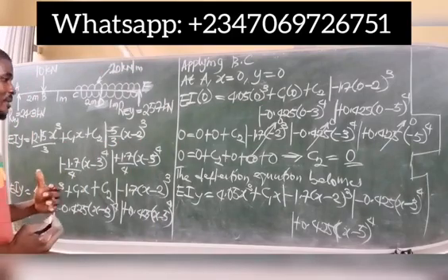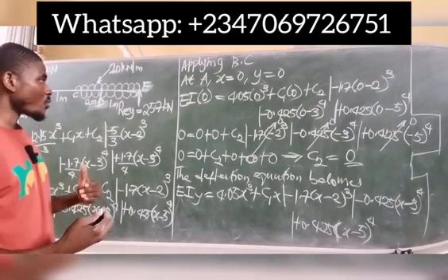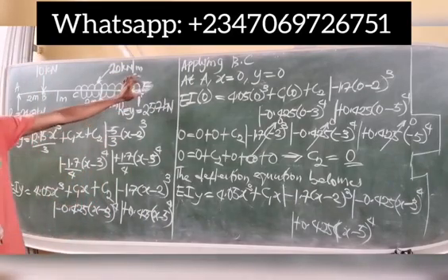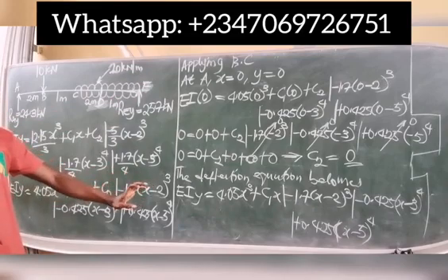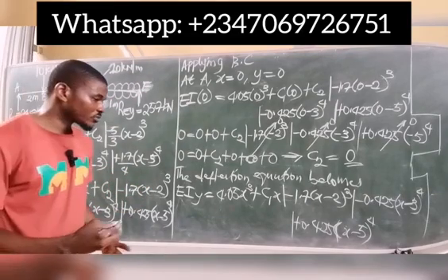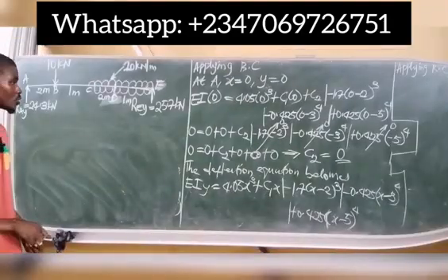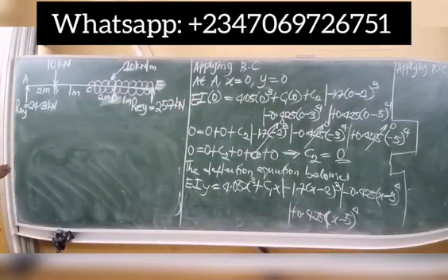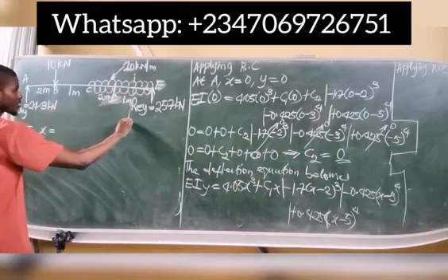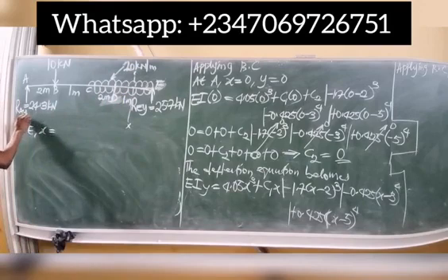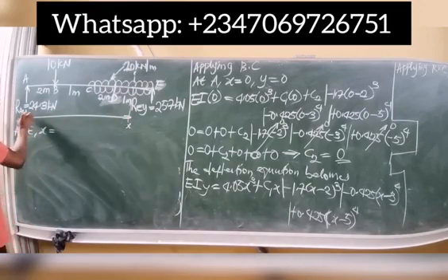So at this point now, we employ the second boundary condition. What is the second boundary condition? Simply at where? Point E. That will help us now to find the value of C1, or the first constant of integration C1. Okay, so let's do this and see. So applying the second boundary condition, which is at the end of the beam E, so simply at E, x is equal to, now remember we took a section somewhere around here, section xx, and we call the distance from point E to the point of section to simply be x.